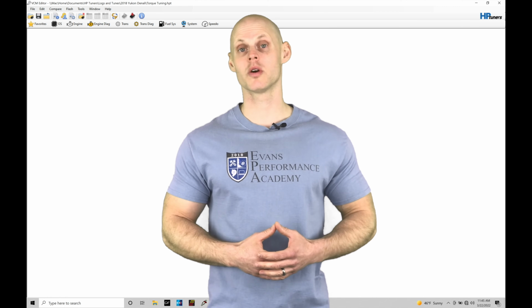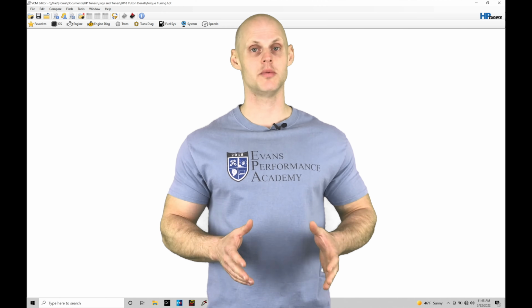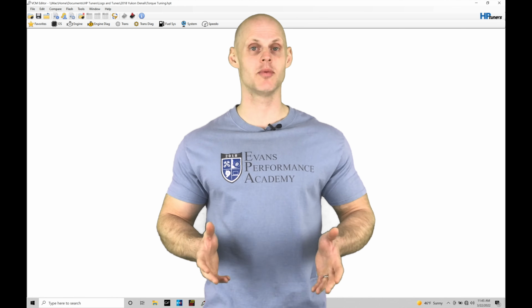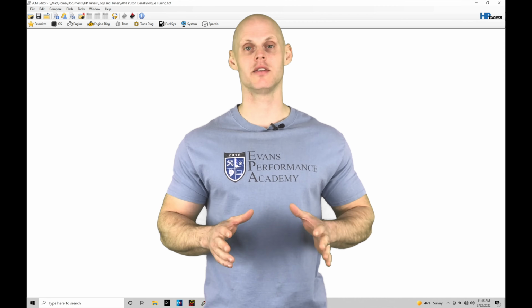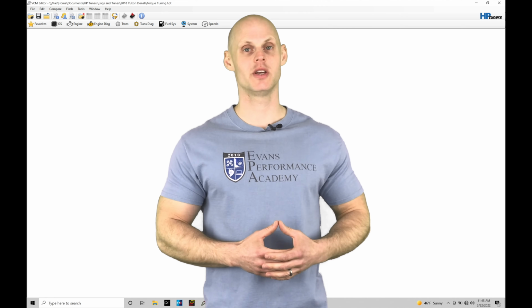In this training module, we're going to be exploring the basics of our idle control. We'll find that the idle control is going to be a torque-based system. We're going to go through the tables, how it works, and understanding the concept of the torque-based control. Without further wait, let's jump in so we can check this out.